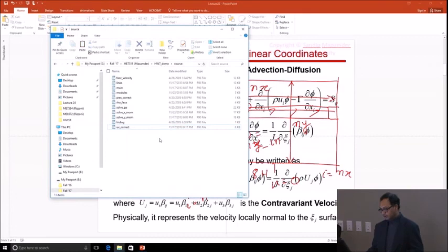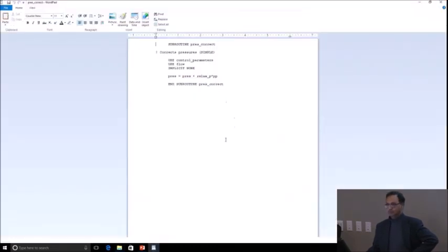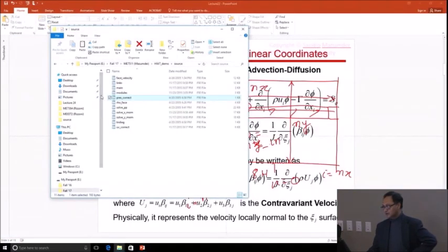So after that, we are basically back to square one. After we've solved the pressure correction and corrected our velocity, the pressure correction is the same as before, one line, no change. You're simply doing omega p times pressure correction. It's a global operation. All the cells get corrected in one shot. And that's it. You're back to square one, back to the beginning of the loop. Any questions?